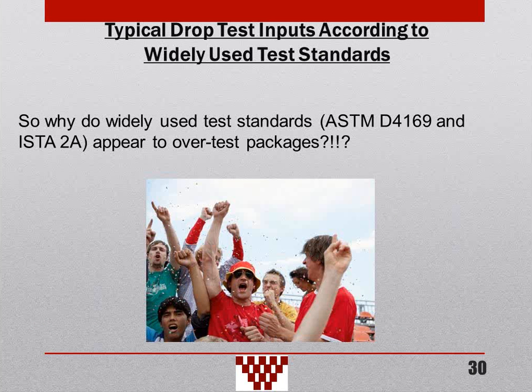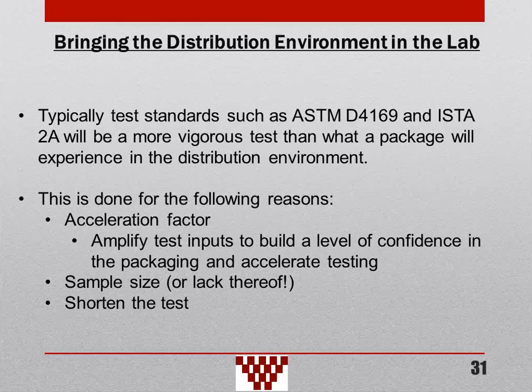Typically, test standards such as ASTM D4169 and ISTA 2A are more vigorous than what a package will experience in the distribution environment, for 3 reasons. The first reason is the acceleration factor, which means we amplify test inputs to build a level of confidence in the packaging and accelerate testing.